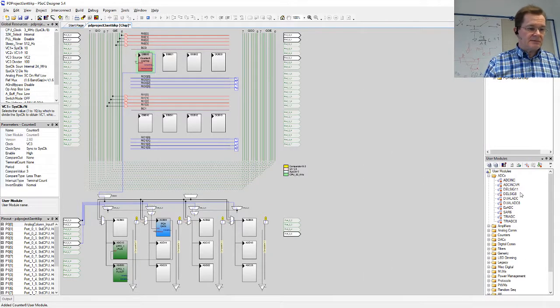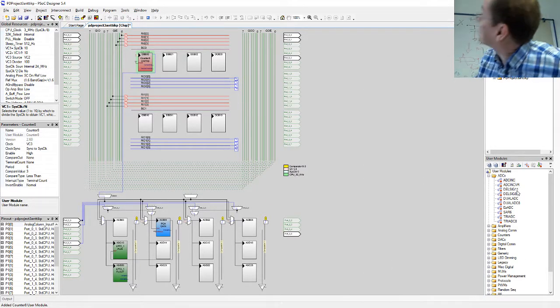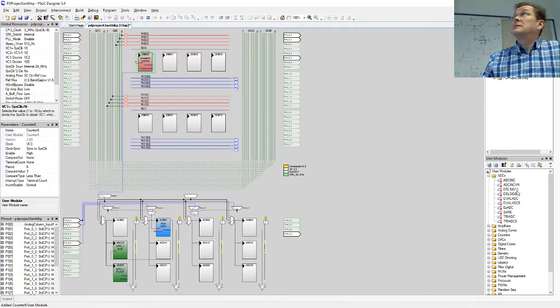Usually, actually, for some reason, these chip manufacturers, they like delta sigma, which is not the best solution ever. It has lots of resolution, but accuracy is not that great. It's because it loses the zero level at some point in any case, unless it's recalibrated once in a while.